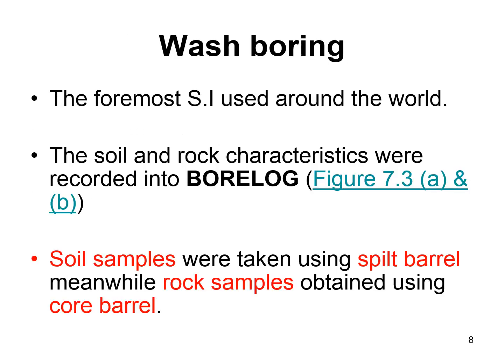Wash boring is a common method in site investigation that has been used around the world. The purpose of wash boring is to obtain the sample. Wash boring is a fast and simple method, and it does not require complicated equipment. For example, a soil sample can be taken by using a split barrel, and a rock sample can be obtained by using a core barrel.